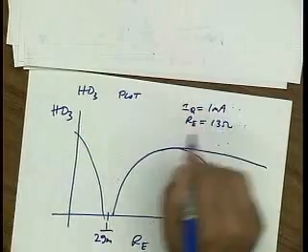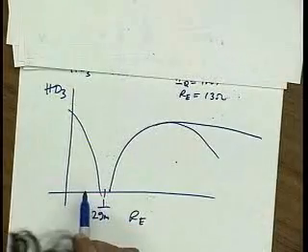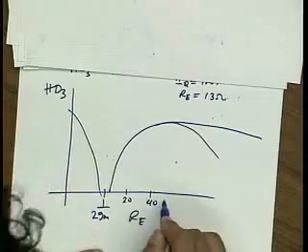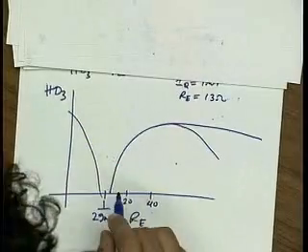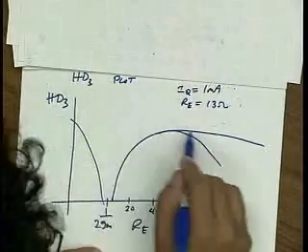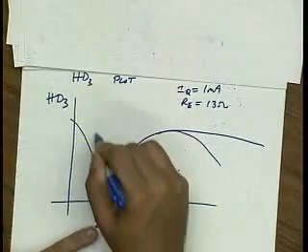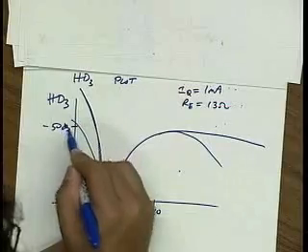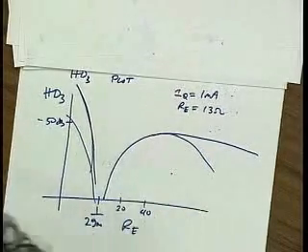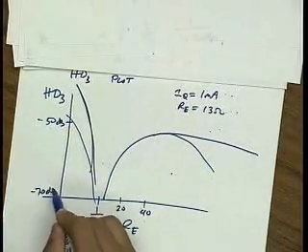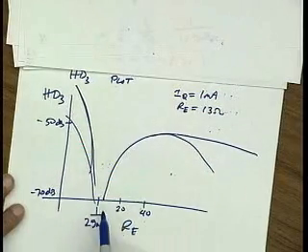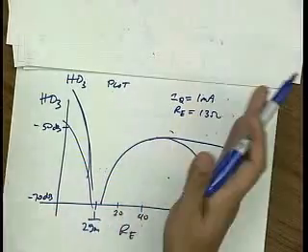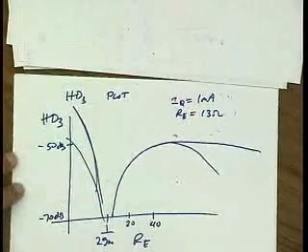So for the null, you need about 13 ohms. So if this is 13 ohms, this is something like 20, 40. This level here is about minus 50 dB. And so the size of this null is quite large. This is minus 70 dB. So the idea is that if you're here and your resistance changes a lot, you go way up because it's a very deep null, very rapid null.